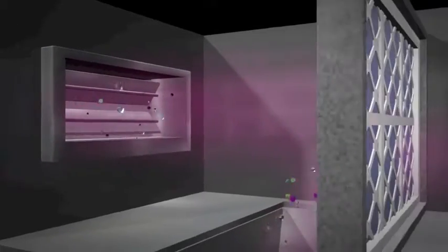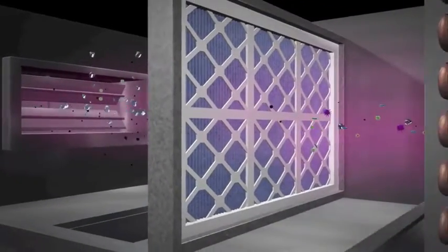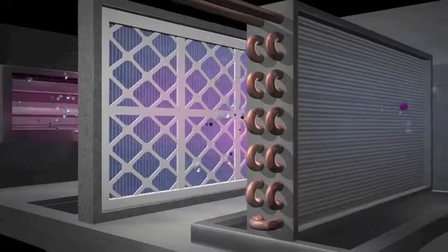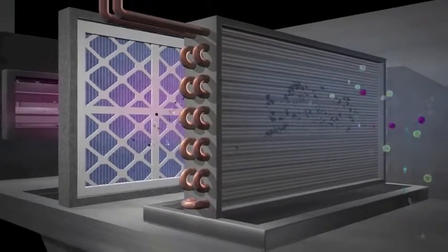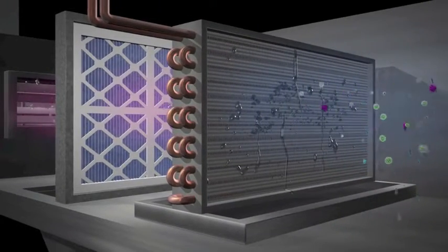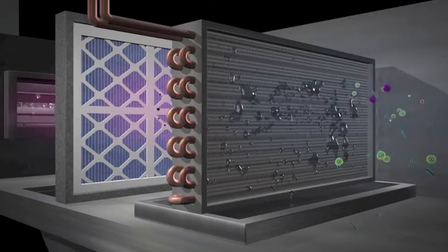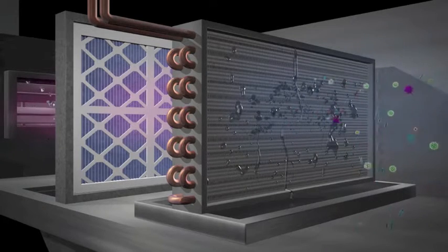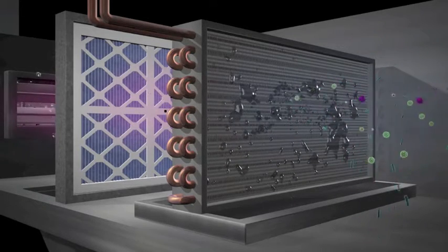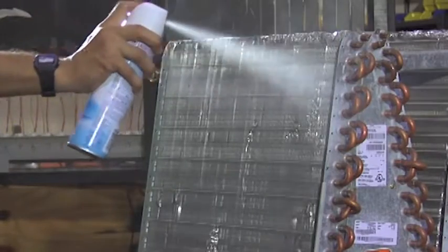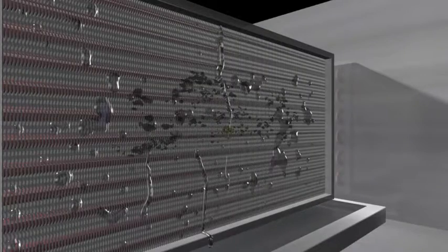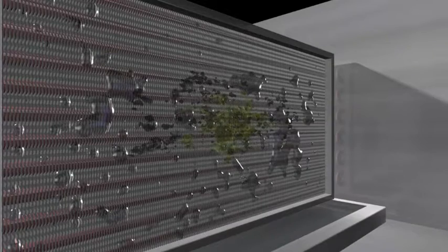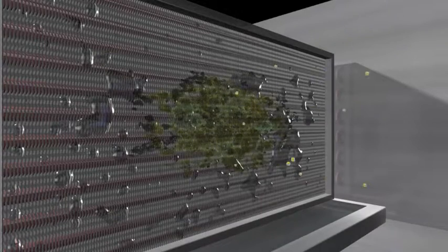When particulates pass through the primary filters and settle on the coil, we should expect the condensate that is produced when the warm air meets the cold coil to wash the particulates down into the drain pan, but the dust stays on the coil and often requires harmful chemicals to remove it. We now know that as soon as the condensate is produced, mold and biofilm start growing.